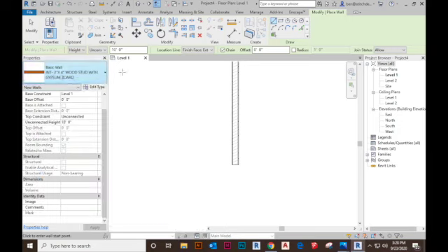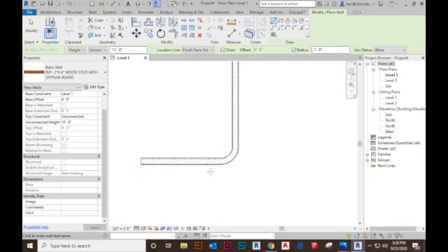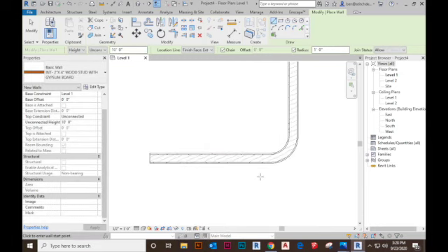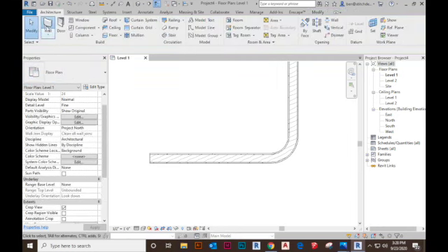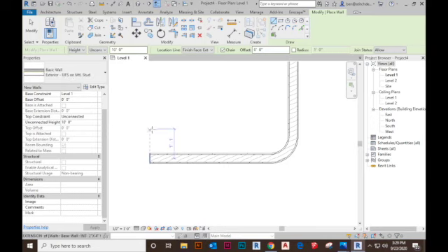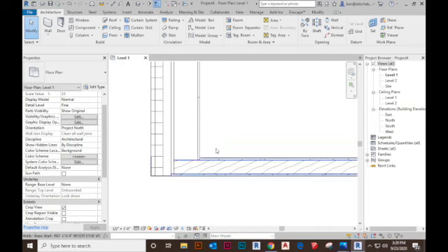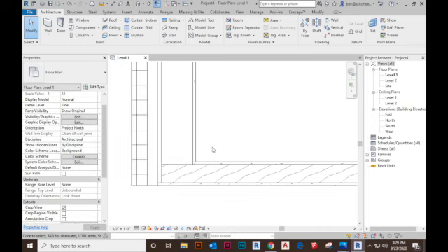Let's select that wall, and this time, let's join it with a radius of 1 foot to the next corner. Again, all of the same materials and all of the same functions joined together. If I select another wall type, such as exterior EIFS on metal stud, and pull from that same wall, you'll see that different wall type functions and different materials will not join together.